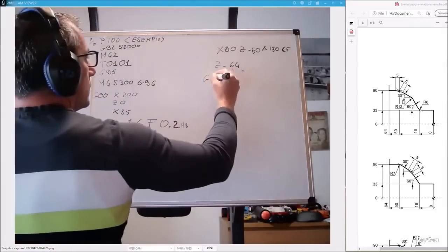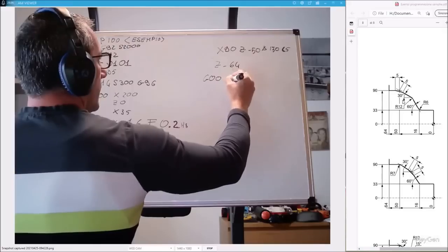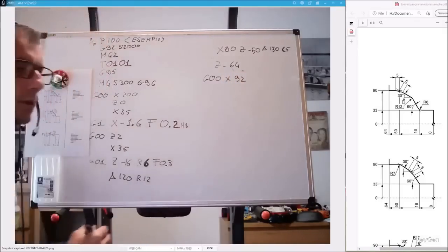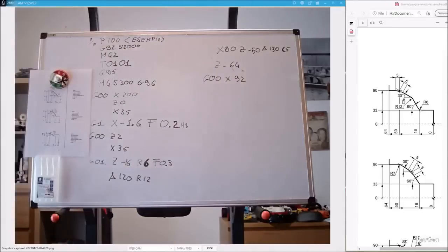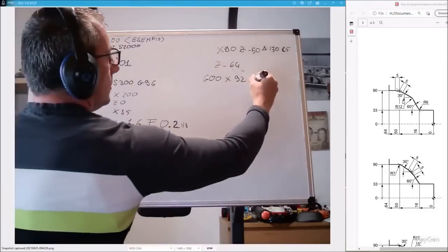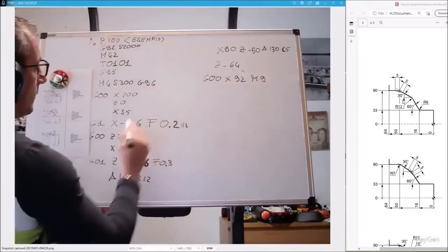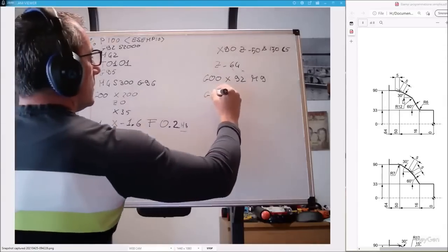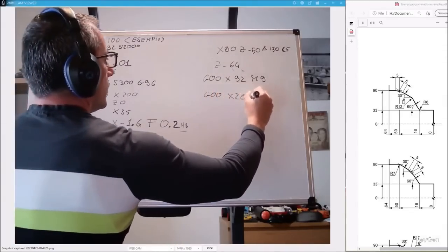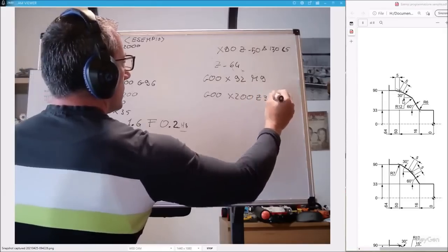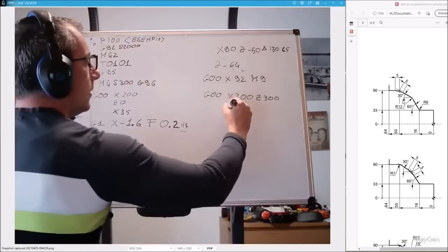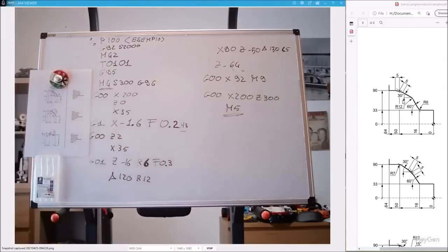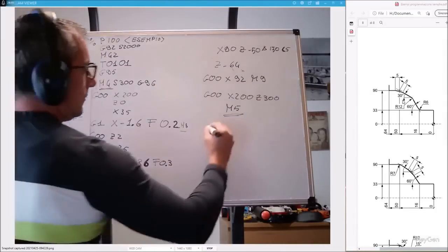At this point, I exclude G01 with a nice G00. I'll put 92 on it. At this point, I have finished the machining. I put in an M9, so I exclude the M8 and stop the coolant. G00 X200 Z300. I move away. M5, I hadn't explained it to you yet, stops the M4, so it stops the spindle. M30 tells the machine I have finished. From the next start, you restart here.